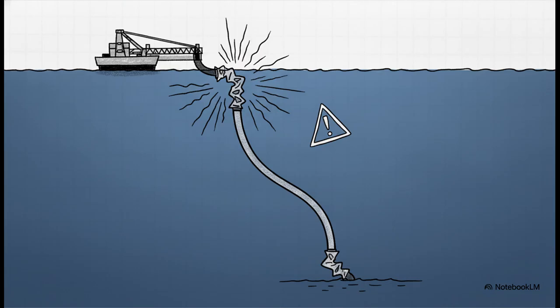But physics always demands a trade-off, right? While S-lay is incredibly fast, pushing its depth limits is dangerous. As the water gets deeper, the suspended length of the pipe gets heavier. The vessel has to pull way harder to maintain tension, which generates massive bending stress in both the overbend at the stinger and the sag bend near the seabed. Push it too deep, and that bending stress exceeds safe limits, practically folding the pipe like a drinking straw.